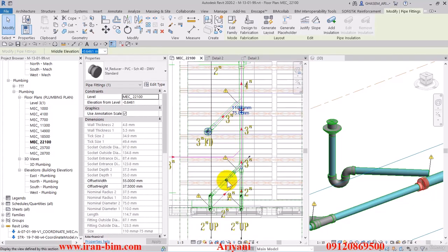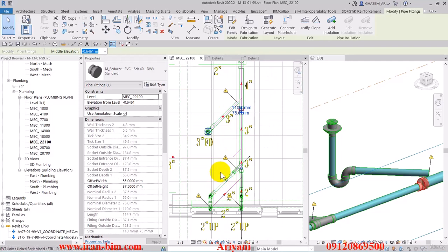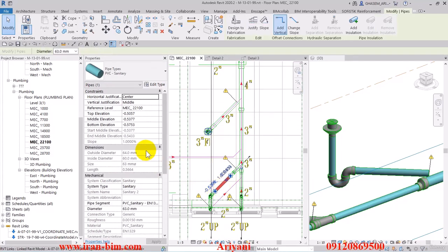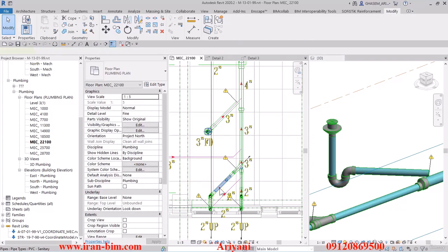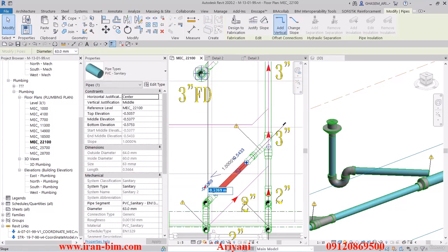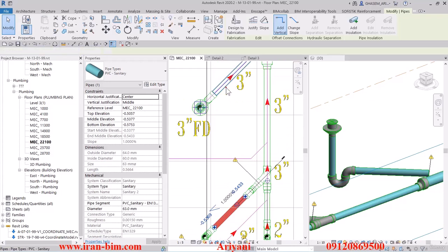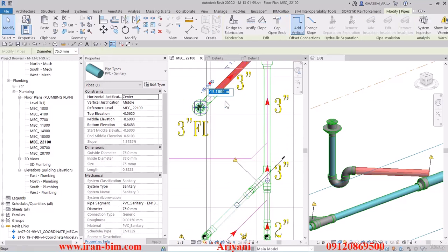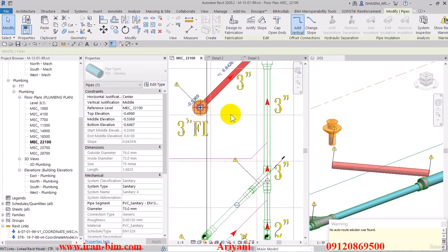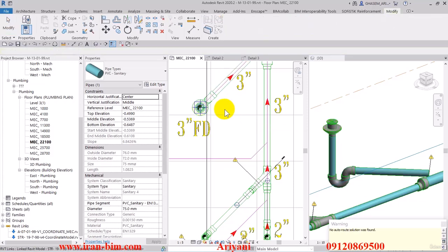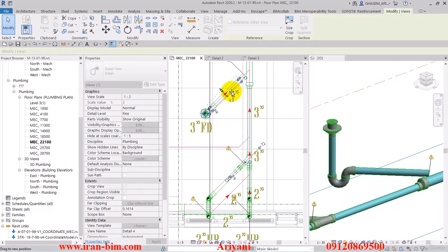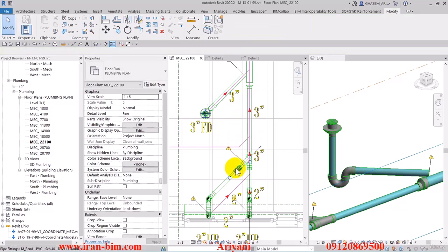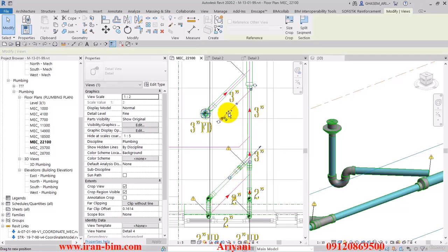And because a vent is going through and underneath this part, we need to move this. So let's see what the elevation of the pipe here is. It's about -0.53. So I'll select the pipe that we have up top. Click here. Ctrl Z. It seems like the levels are differentiated here. Now I can move this section upwards, or I'll hit Ctrl Z and get a copy of this section.